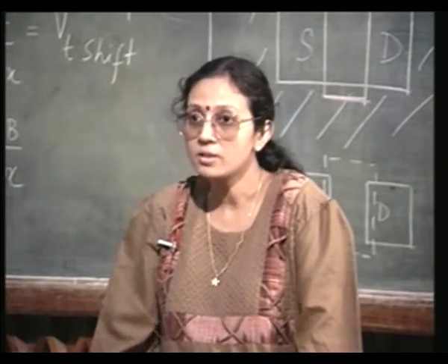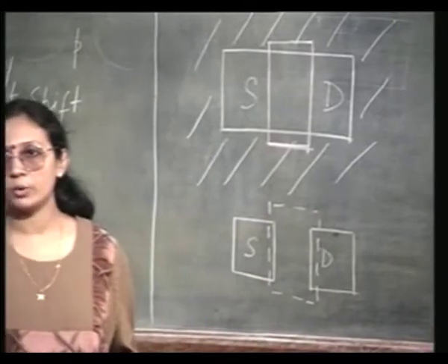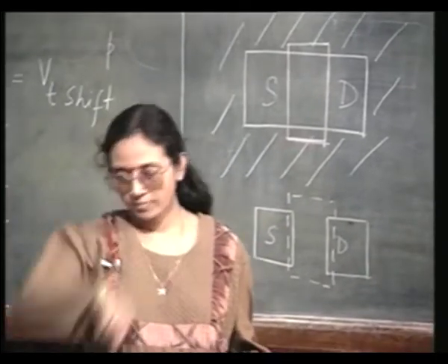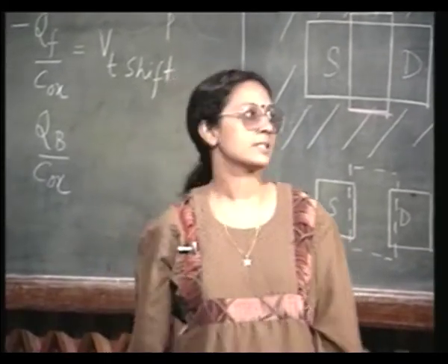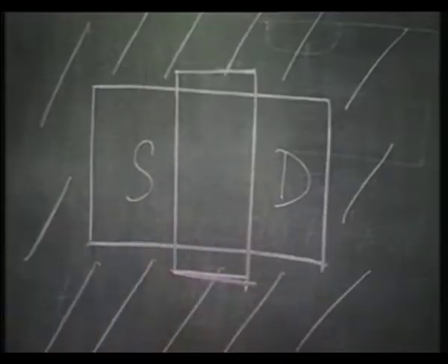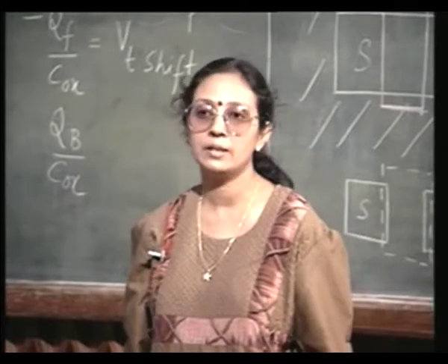That was the reason why here we had to do the source and drain first and then follow it up with the gate. So, the idea is, if I want to have a self-aligned gate to source and drain, if I want to have a self-aligned technology, I can no longer use a metal gate.